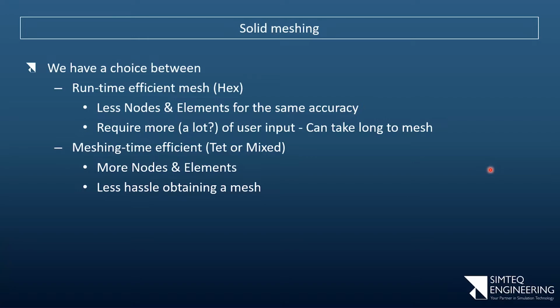On the other hand, if you do a nonlinear analysis where it needs, in some cases, hundreds or thousands of iterations, every iteration is a linear static analysis. So where the previous model I ran for a day, if you now do 10 iterations, it will take 10 days to do. So for a lot of nonlinear analysis, we tend to try and spend a lot more time and effort in getting the runtime down, which means we spend more time meshing.